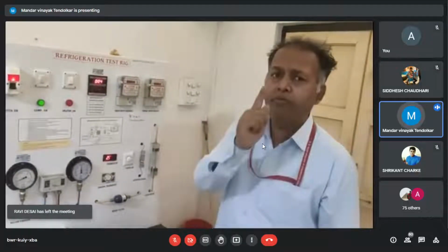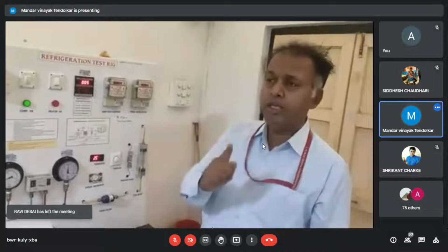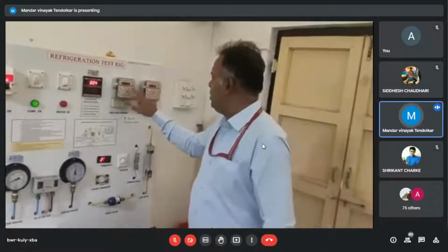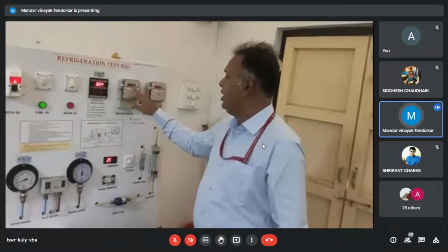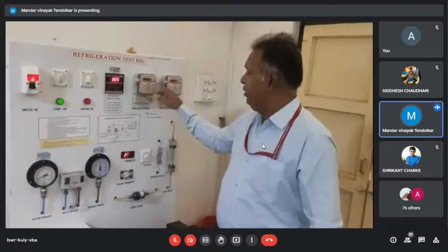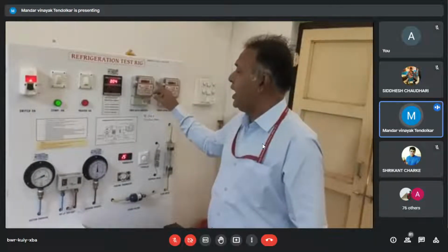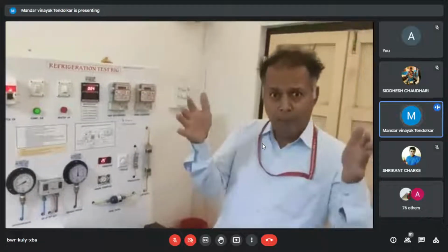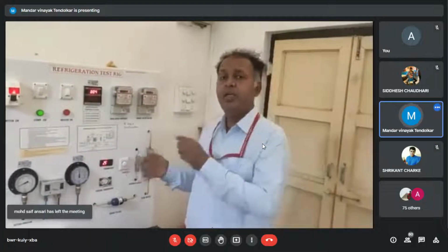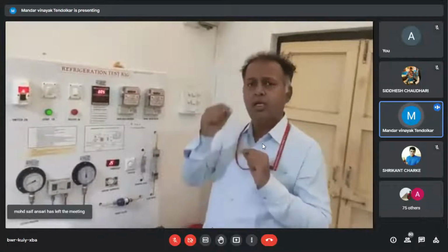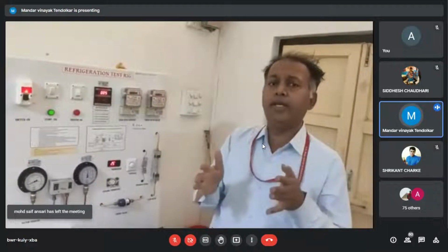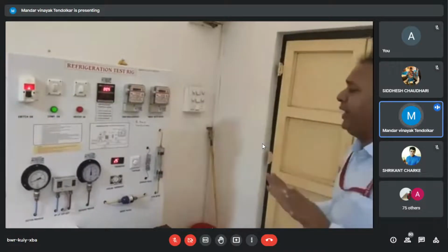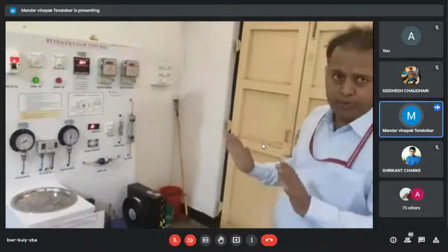You know that one unit of electricity is 1 kilowatt hour. So 1 kilowatt hour is the unit of electricity. So accordingly, one can read the meter and one can find out how much kilowatt hour is consumed by this compressor in a given time. And upon the time of the conduction of the test, that is kWh upon time in hours, the hours will cancel, and what you get is the kilowatt rating of the compressor. So this is how experimentally one can find the compressor power consumed.